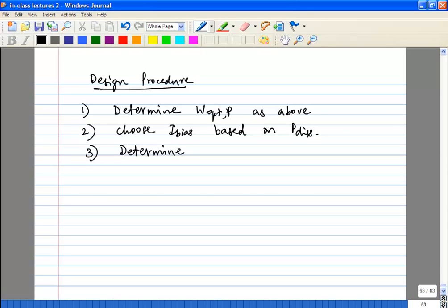So the thing to remember is, obviously I have not put in the length of the transistor. I'm assuming that you're going to use minimum length because you want maximum FT, and you would normally want to do that if you want to hit minimum noise figure. Once you have these two, you know CGS, so then you can calculate LS, which is your source inductance to match, because once you determine I bias and W opt, you already know your omega T. Omega T times LS is RS, which in this case I have assumed is 50 ohms.